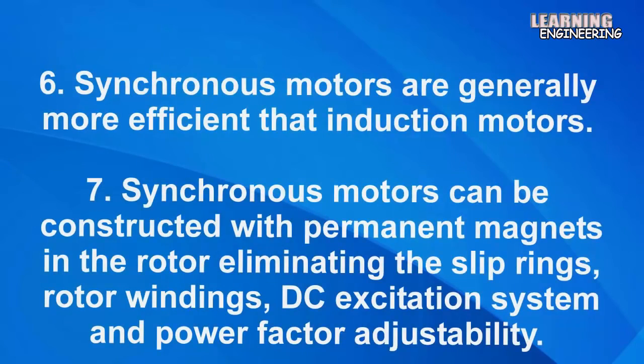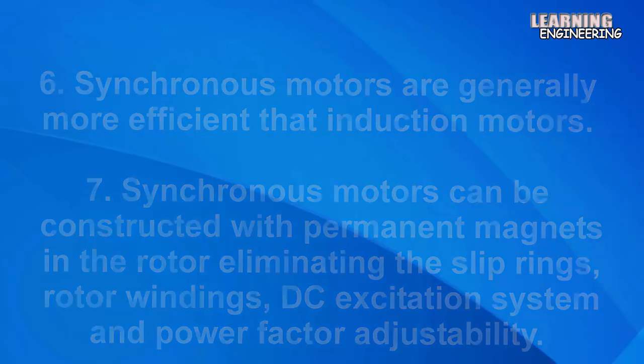6. Synchronous motors are generally more efficient than induction motors. 7. Synchronous motors can be constructed with permanent magnets in the rotor, eliminating the slip rings, rotor windings, DC excitation system and power factor adjustability.